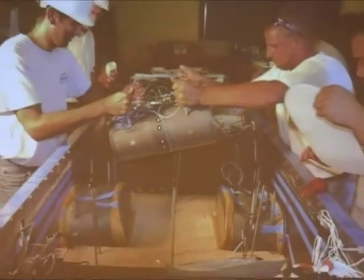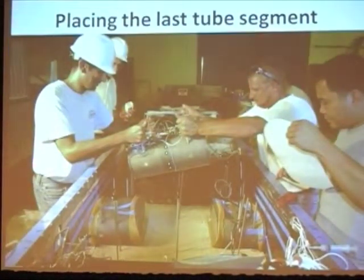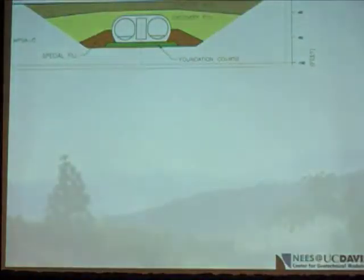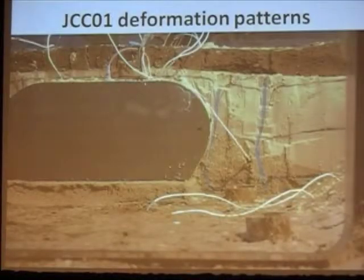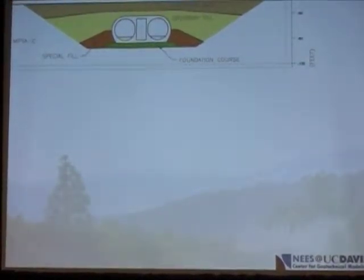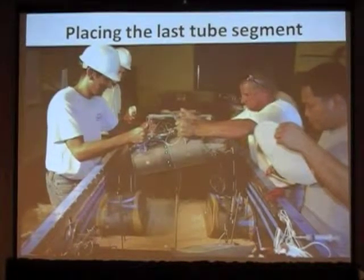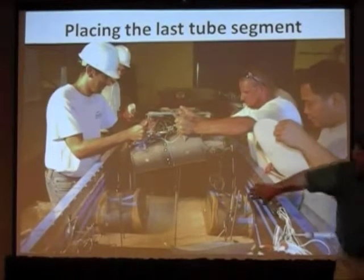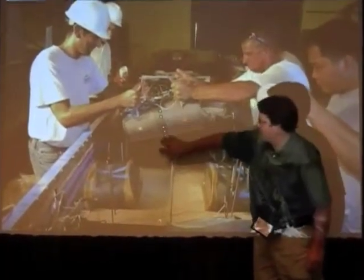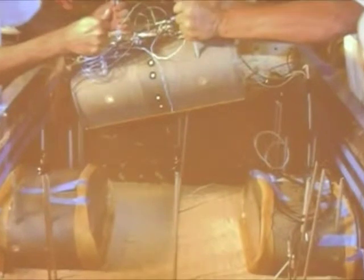And then just an idea of how much work is involved in putting these things together. The tube while it's going in, and there's a really good picture of the model there. Not on this one, unfortunately. So just showing you this, I wanted to point out you can see some of the sensors in here and the complexity of the model that goes in. These are pore pressure sensors that are actually buried in the tube. There are the displacement flags and things on the tube.